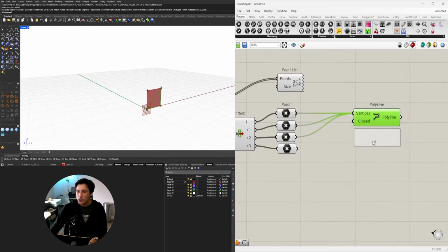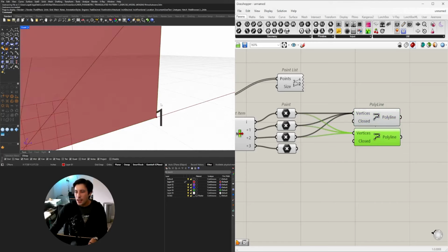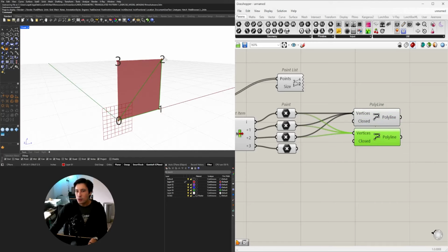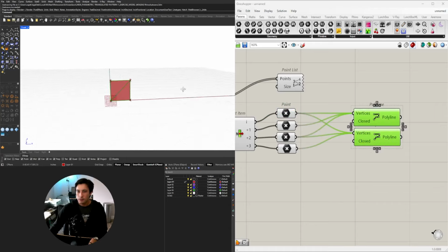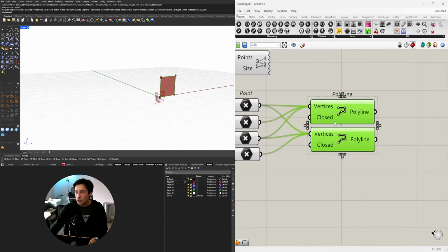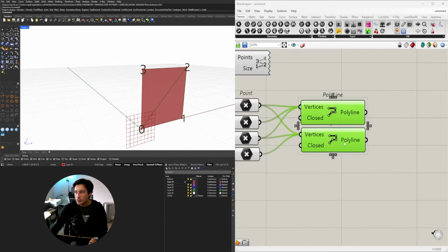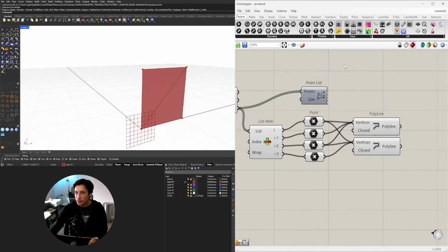Now let's do the other triangle. So I'll take this, tap Alt, and create a copy. And notice that it goes 0, 2 to 3, and this one went 0, 2, and then 1. So what we need to do is unplug this and plug in 3. So hopefully you saw that. Otherwise, we can always undo this and just go 0, 2, holding down Shift, and then 3. So notice that now we've triangulated or subdivided this triangle using the points of that panel.